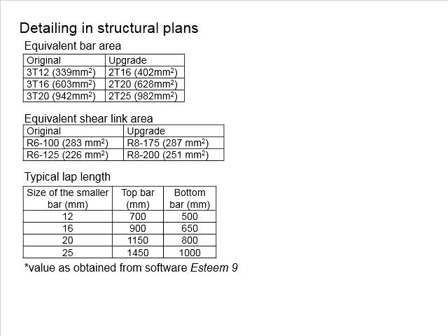The reason that sometimes you choose to reduce the number of reinforcement bars is so that your beam sections have larger space, especially in consideration of the minimum spacing between the reinforcement bars, which is meant for the pouring of the concrete and compaction of the concrete during casting. What you see here is something interesting: you have 3 units of T12. You can actually change it to 2 units of T16. You reduce 1 unit of the bar, but increase one size of the bar.